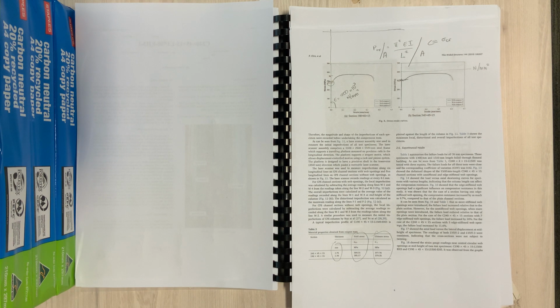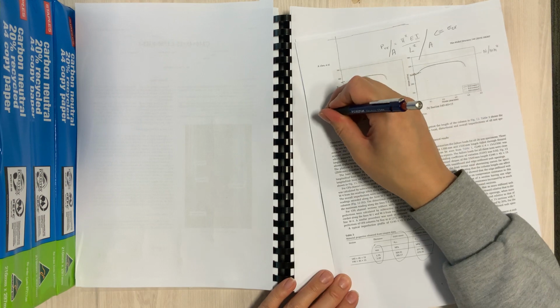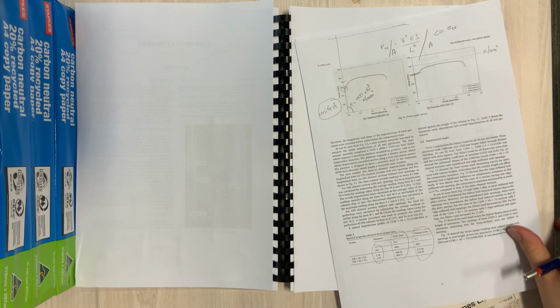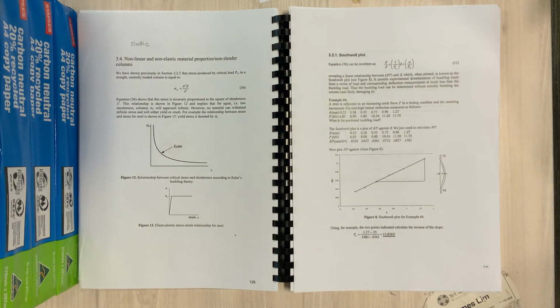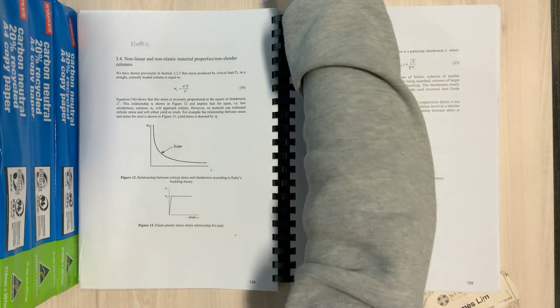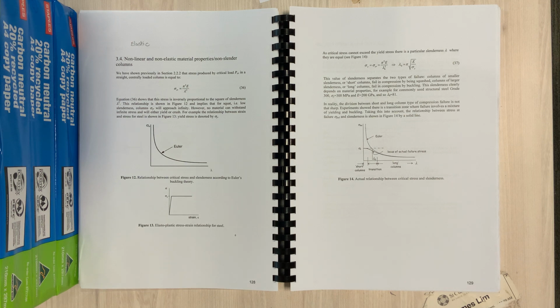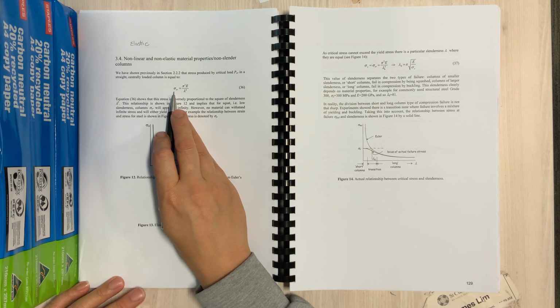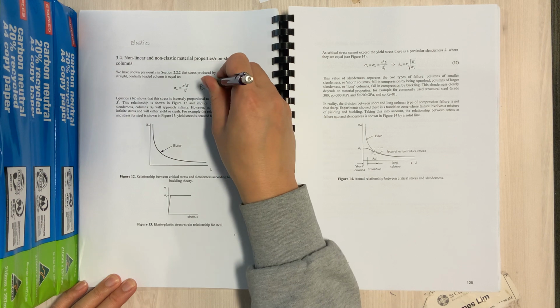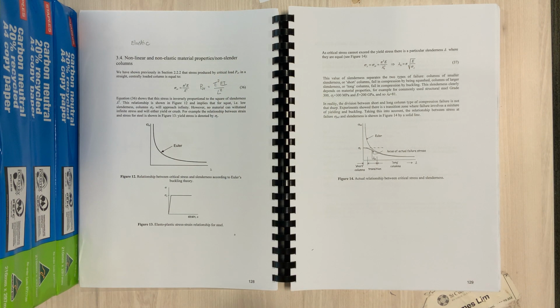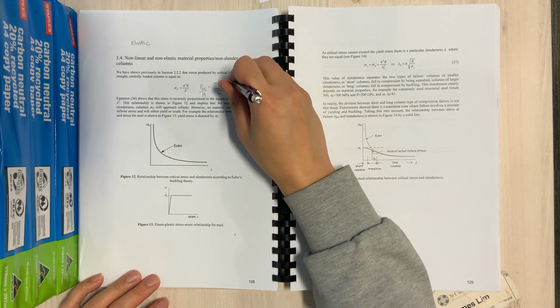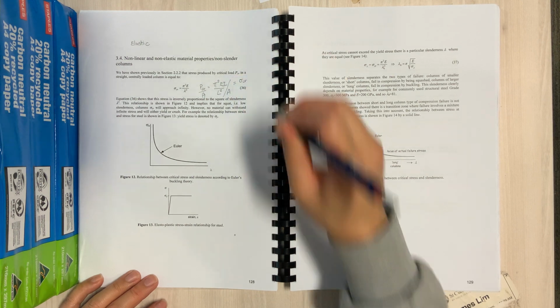So now we come in terms of our discussions, and we want to talk in terms of maybe a unified approach. A unified approach means that we wish to take both the material capabilities or the material strength as well as this buckling into account when we come up with some design guidance for columns. So we've already shown that PCR is equal to pi squared EI over L squared, and we've said that's all elastic, and then we've talked about the slenderness before, about combining the L and the radius of gyration for the slenderness, and then if you divide the PCR by A, we're going to be getting the elastic critical stress.